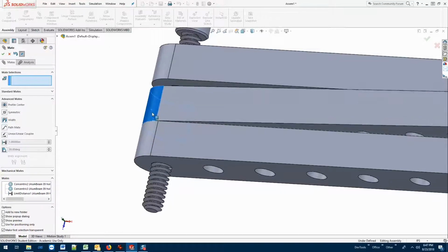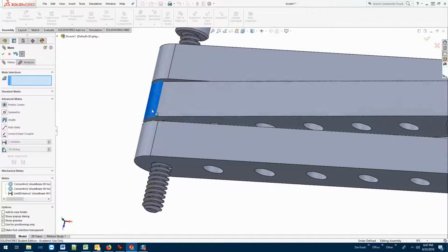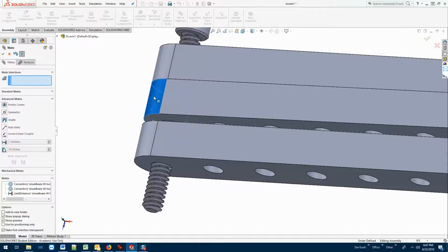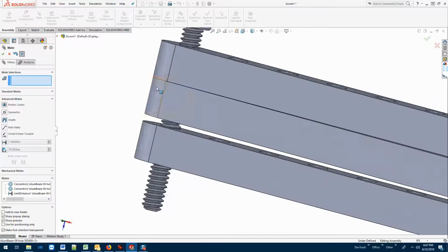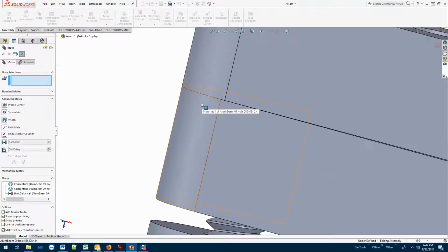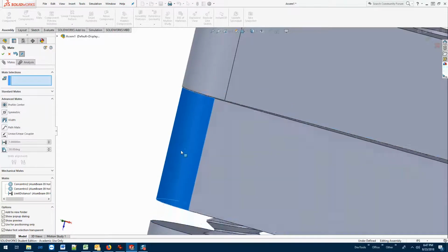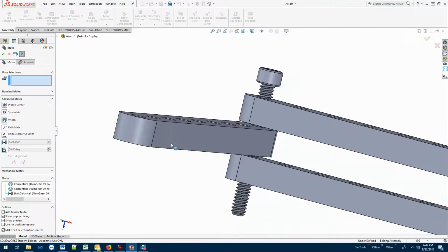And that's a mate. And it'll slide back and forth on here. It'll get to this point, and it looks like the other beam is what's physically stopping me. But what's physically stopping me, as we could see, is this mate that I set up that is a limit distance mate. So it gives me that ability to allow parts to move, but constrict their movement in some way.